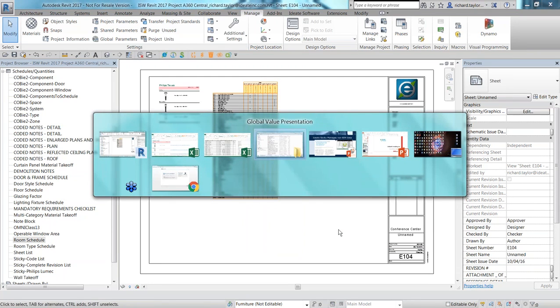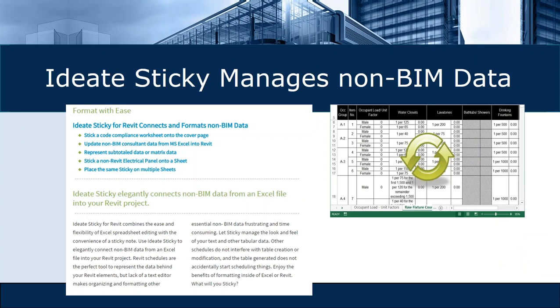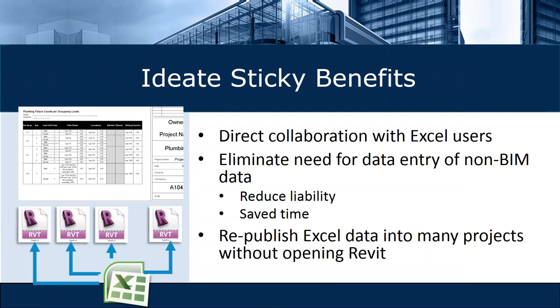So that's Ideate Sticky. I'm going to go back to my presentation here. And again, managing the BIM data or the non-BIM data, allowing you to publish an Excel worksheet in your Revit project. And in fact, you may have general notes that are linked into 5 or 10 different Revit projects. If you update the general notes in one location, then that's updated everywhere on all 5 or 10 of those projects.